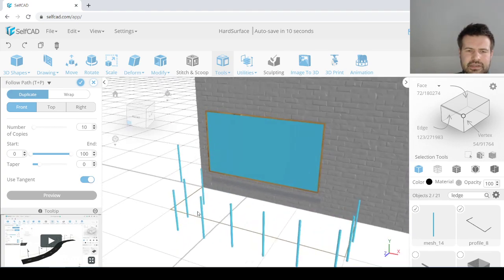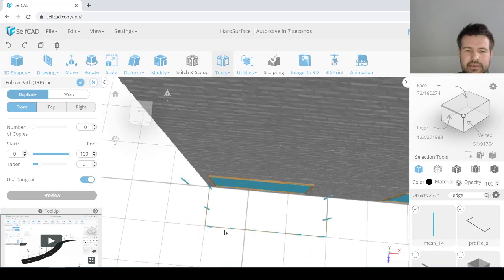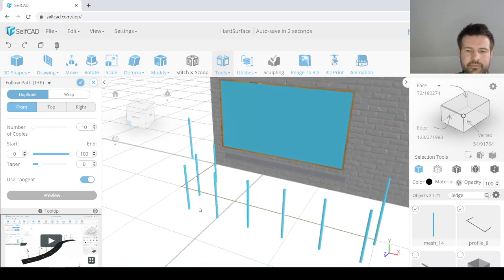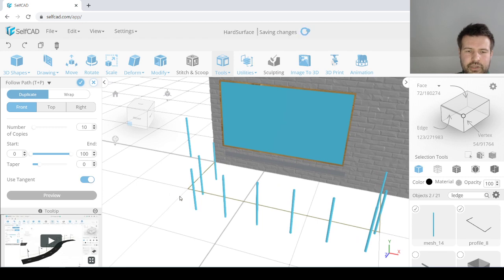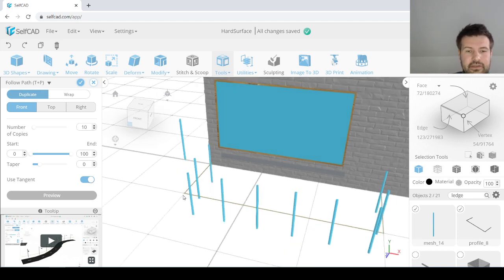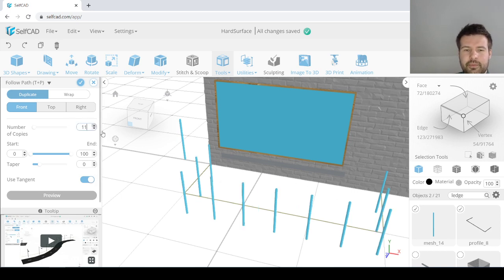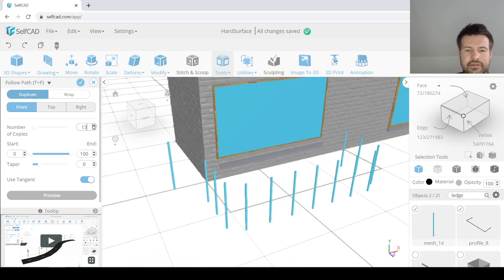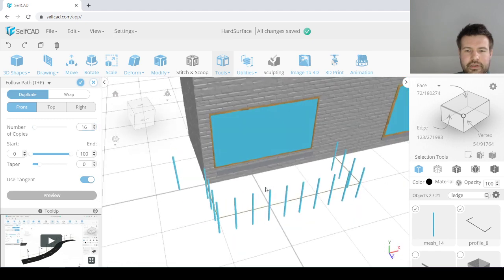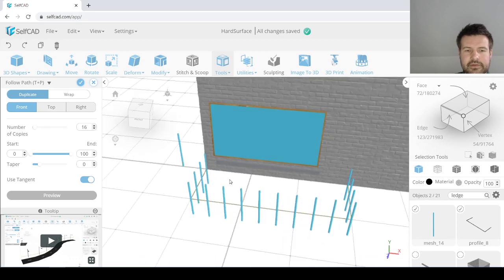The reason why it looks like it's not really on the path at first is because it's a little below the grid, and this will get fixed by itself by our software, because we keep everything on the workspace. So I could draw the railing a little higher just to make the effect correct straight away, but you can see that it created copies around the railing. So the only thing we need to do is get a number that makes it more or less correct. I think 60 should be a right amount. So we'll have four elements here.